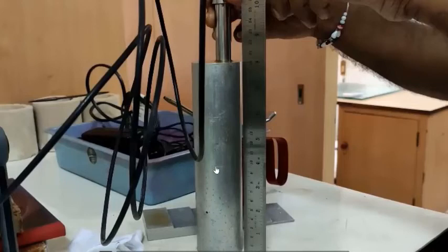Along that line on the other side you have one more hole at equal distance. From this hole to the second hole it will be again 50 mm. And here also you can see one more line. Along this circumference, at this distance, again 50 mm apart from the second hole, you will have another hole drilled on this block. So apart from this back wall signal, if the transducer is kept right over these holes, at an appropriate place on this top surface, you should be able to see some echoes corresponding to these holes also.